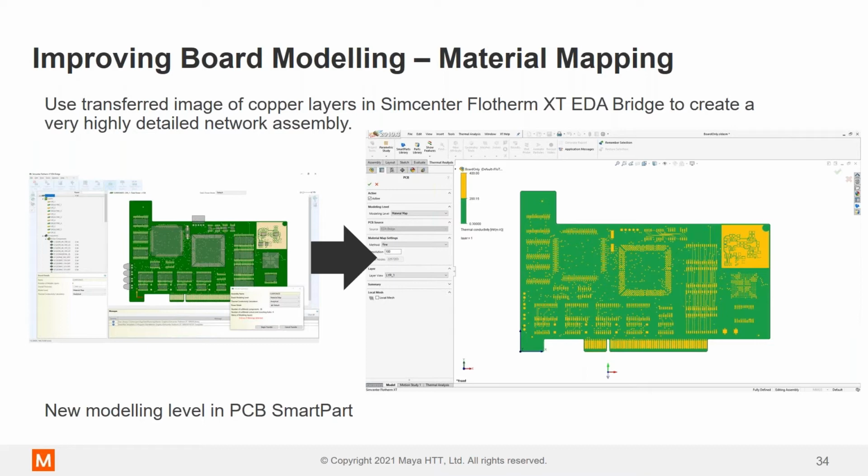This is very easy to do because the board, the conductor, the dielectric is well defined. We don't have to worry about convection in the board. It's only conduction. So we can create a matrix of conductances, a little bit like a Delphi component, but with a lot more resistances. And this is done automatically for you in the Flow EDA bridge. Next slide, please.